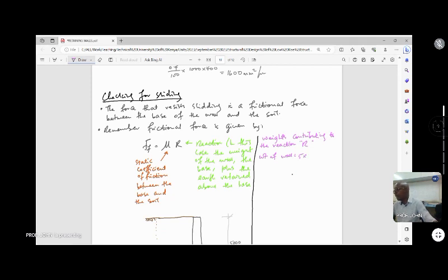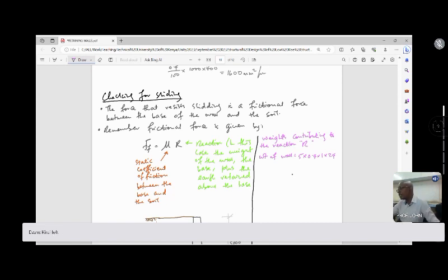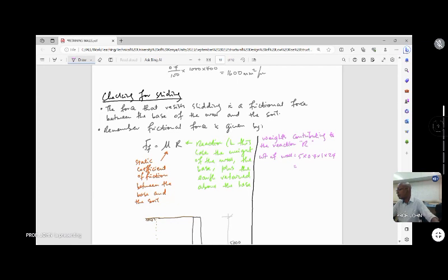5 meters by 0.4 by 1 meter by the density of concrete, to the BS, because to the Eurocode it's 25 or 24 and a half, depending on the state of the concrete. So we're just using the value to the BS. So 5 times 0.4 times 1, that's the volume of that 1 meter strip of stem that you're considering. Then we're multiplying that by the density and we get 48 kilonewtons. And we come to say weight of base.